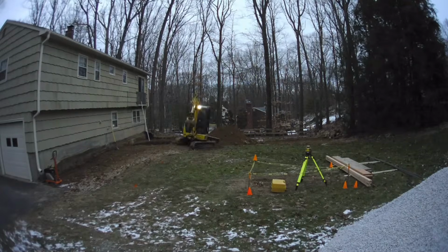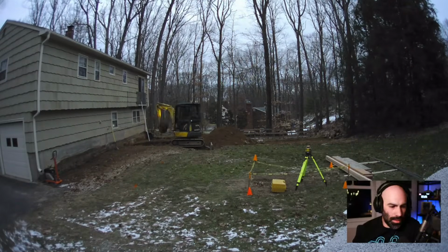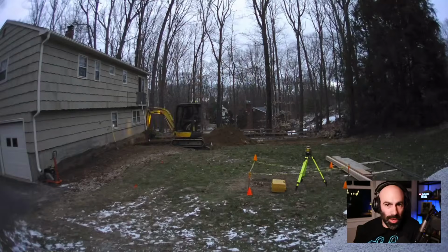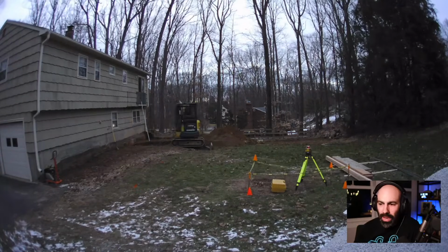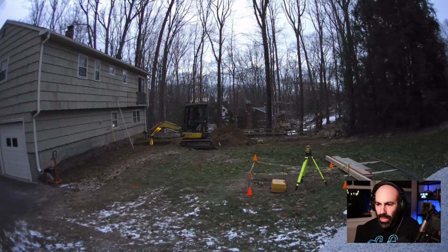Instead of stepping footings, this was a nice little sort of cost saving thing. We just went down to the lowest footing on the right hand side, or this north side, I guess it would be, and just made it a straight footing all the way across. Instead of having a whole bunch of steps to get down to the bottom, it just made sense on a small footprint like this.